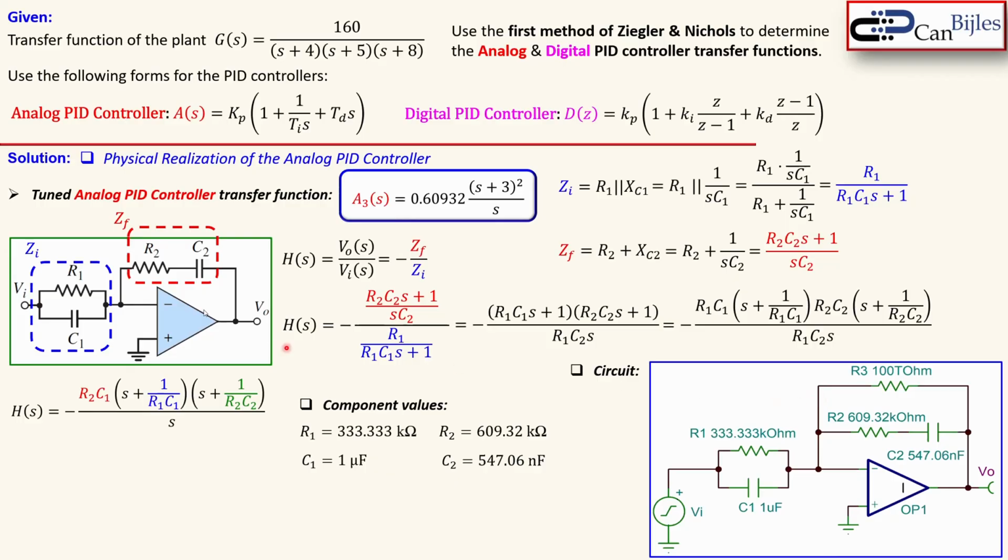So what I do, of course, we have here an open loop, not a resistor or something. What I put here is a 1 tera ohm, which is a very large resistor. So instead of keeping this perfectly open, I have put here a very, very large resistor. So it is not really affecting our performance, but still will run the simulator. Otherwise, the simulator will complain about that. It will give you an error. So that's how you can solve that problem.